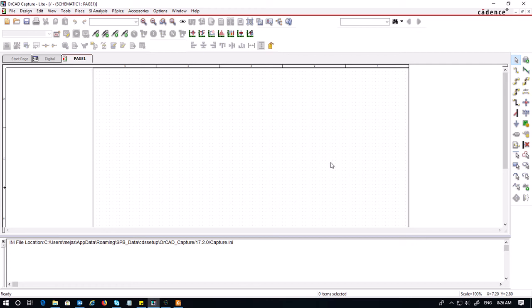So I'm assuming if I use gates from the 74LS library, it may still give me the component error, because in the older PSpice Lite version, the 74LS library was not part of the version. Hence, even if I included that library, it would still give me an error.